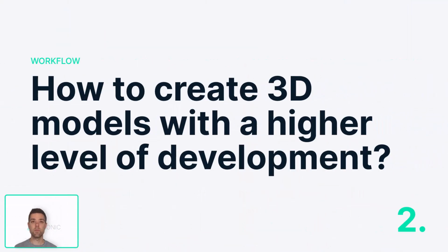The next workflow that we would like to demonstrate is the 3D modeling. So how can we create 3D models with a higher level of development? Of course, as said before, it is our goal to create a full BIM solid modeler. For solid modeling, there are two main approaches. On the one hand, you have direct modeling approaches with push-pull operations so that you can create any shape in a flexible way.